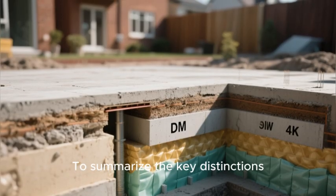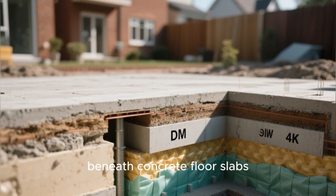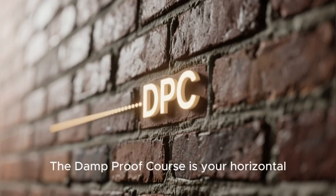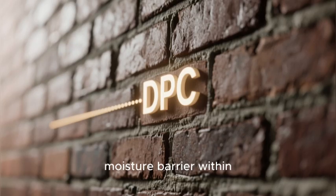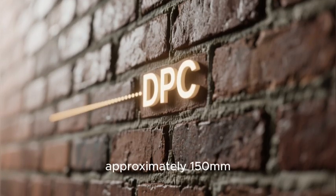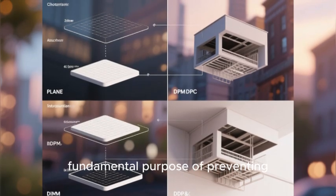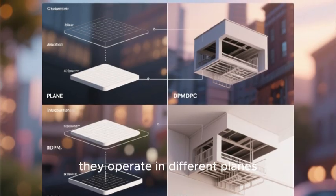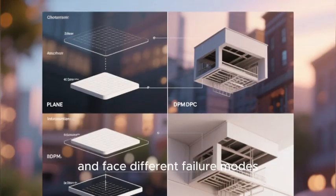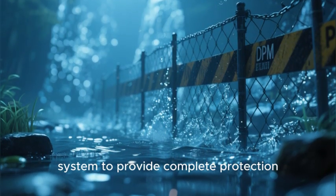To summarize the key distinctions, the damp-proof membrane is your horizontal ground moisture barrier beneath concrete floor slabs, typically a polyethylene sheet installed before concrete placement. The damp-proof course is your horizontal moisture barrier within masonry walls, typically a flexible strip material installed during wall construction approximately 150 mm above ground level. While they serve the same fundamental purpose of preventing moisture rise, they operate in different planes, require different installation techniques, and face different failure modes. Most importantly, they must work together as a continuous system to provide complete protection.